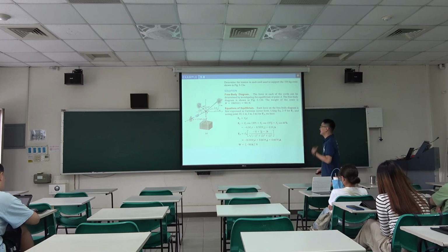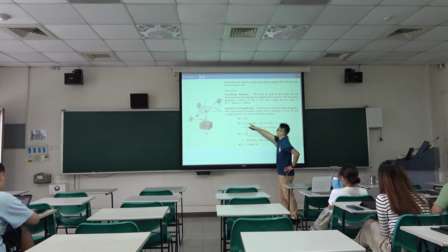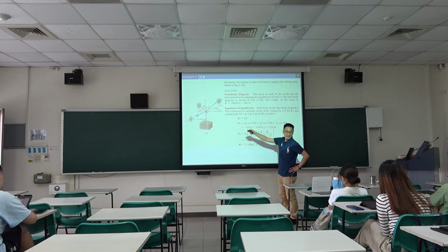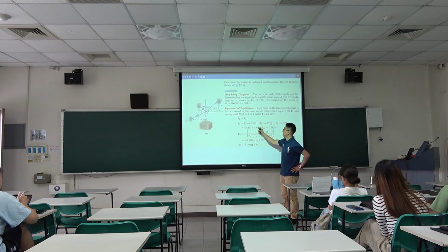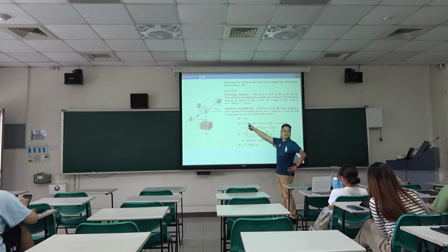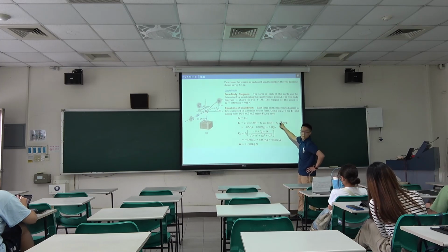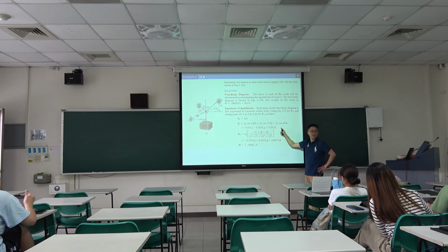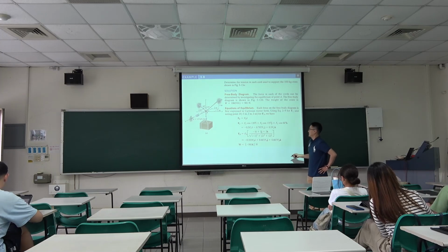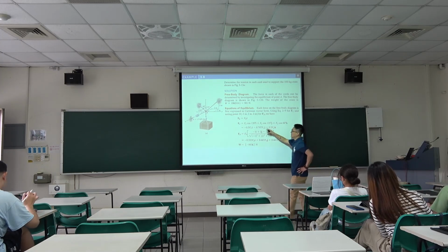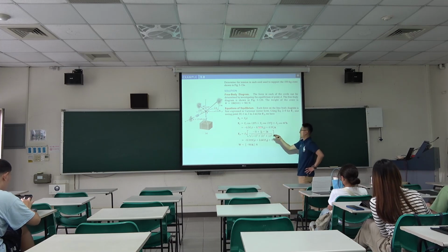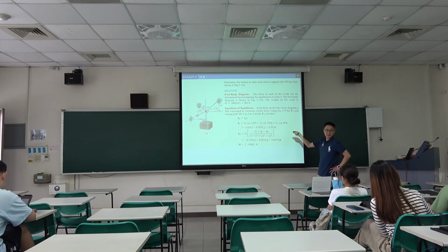For FC, we work out a unit vector relying on the angles alpha, beta, gamma. Cosine alpha is the unit vector component for the x direction, then cosine beta, cosine gamma. So we use the angles to work out the unit vector, and we can represent FC using Cartesian vector based on this equation.